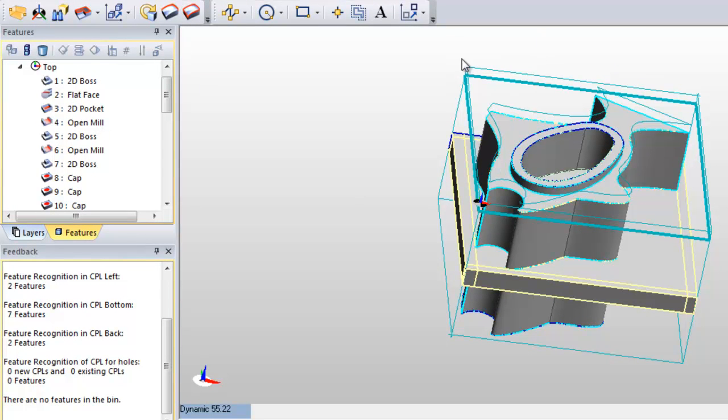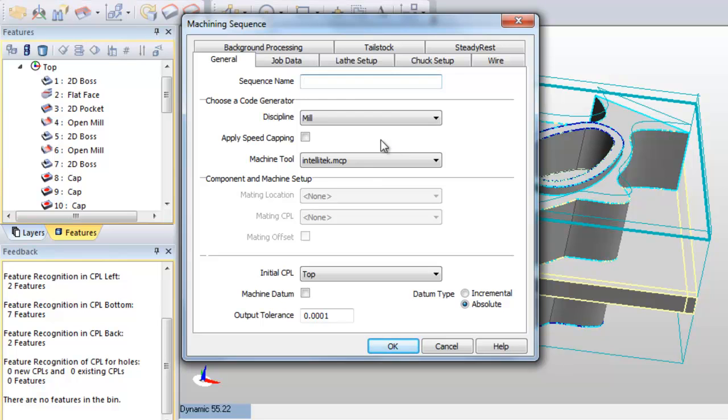So this is EdgeCam, but it's the editing part, or the design mode, of EdgeCam. We now need to go to the manufacturing mode of EdgeCam, and there are two little icons in the top right hand corner. One is the pencil, which is the design mode, which we're in now. The other looks like an end mill bit, and that is the manufacturing mode. So we now need to click over here.